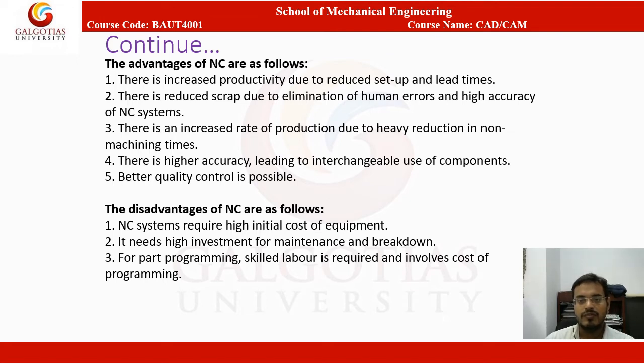So the rate of production also increases due to high reduction in non-machining times. So there is high accuracy leading to interchangeable use of components. Since there is high accuracy, we can interchange the components according to requirements and certain design changes. So better quality control is also possible in the case of NC machines.